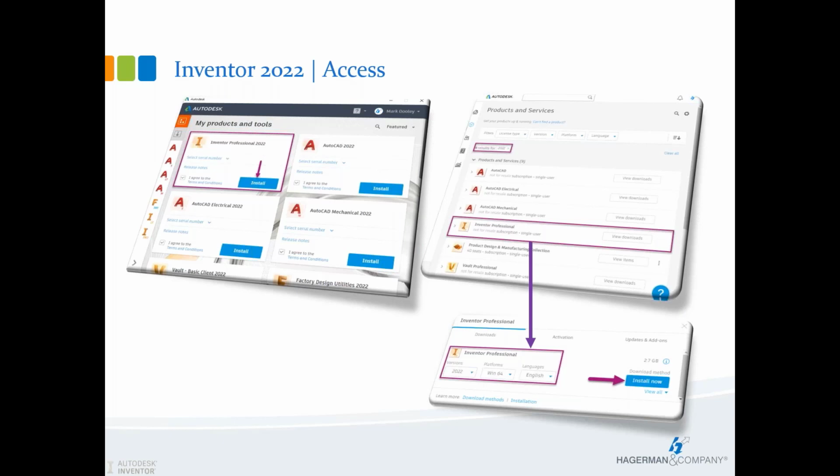So the best way to update iParts and iAssemblies to model states, well, you have to remove the iPart tables and the iAssembly tables. So make sure you've captured all that information, have a screenshot, or have it saved in Excel somewhere that you can pull it back in. But you do have to delete the table from the model itself to be able to work with model states.